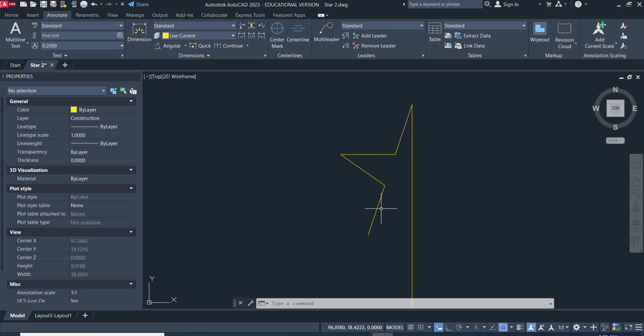And the vertical line is going to be a 90, so you just kind of do the math to come up with that. And you just do it, okay? I'm not going to work through this whole thing. That's part of this exercise, for you to figure out what those angles need to be. You've got 2 horizontal lines that you can draw. That's easy. Everything else is going to be using the line command with the at symbol, a distance of 2, tab key, and then a positive or a minus angle. And that's it.